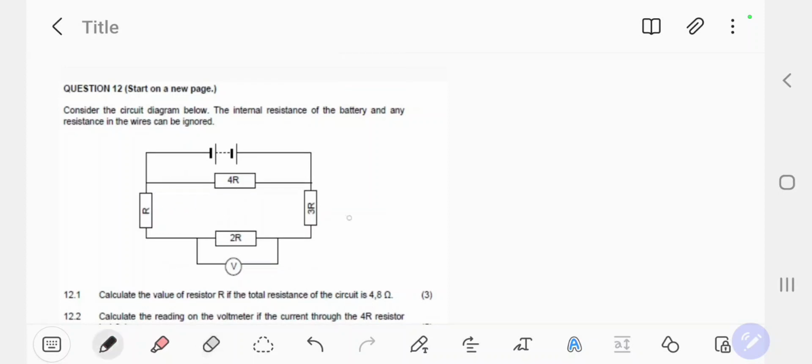And then as a result, guys, we are going to look at this one, and also the R there, to be connected in series. And because they are connected in series, it means we can add them so that we've got a single resistor there. So 3R plus 2R plus R equals 6R. So now the new circuit after adding 1, 2, 3 is going to look this way. We're going to say this one is going to be the 4R, right? And then the next one, which is going to be the 6R, is going to be this one.